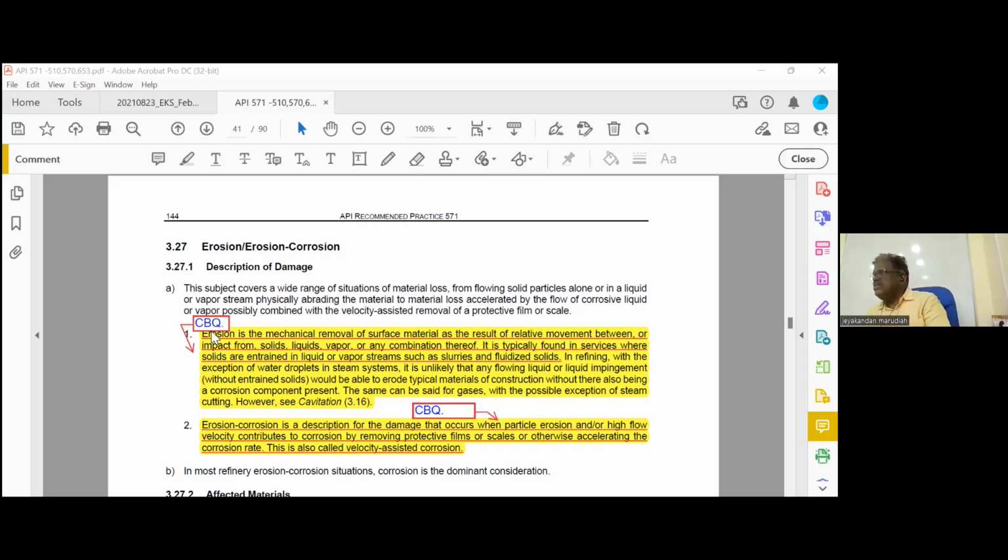The definition of hardness is resistance to indentation by plastic deformation. For example, if you are pressing a surface or hitting a nail, and it is not going in, then it is a hard surface. Inside it may be soft also, but the surface is hard. How will you improve the hardness? By adding carbon. When you add carbon, hardness will increase.